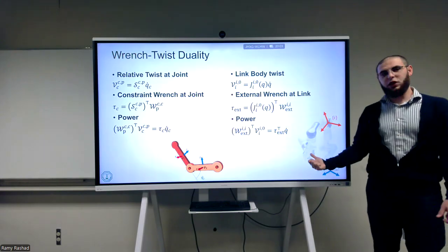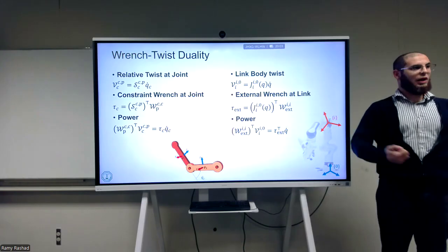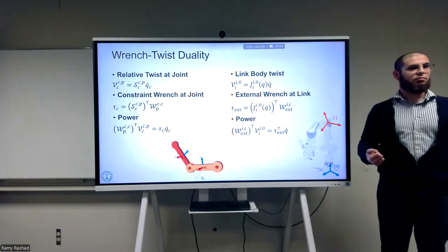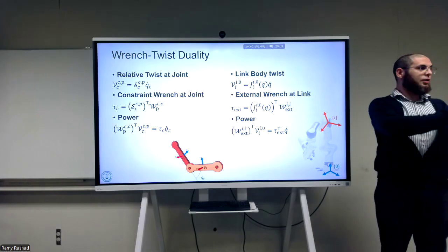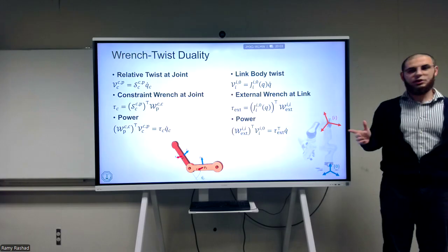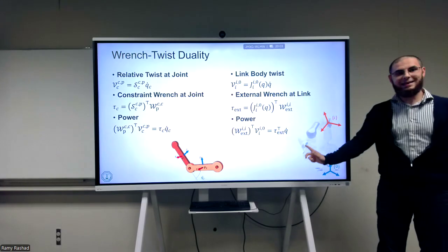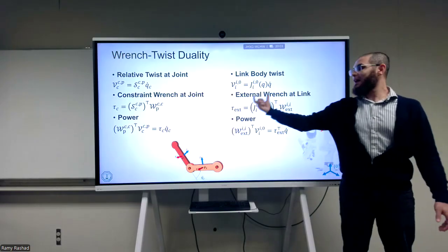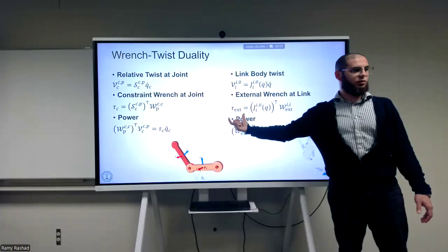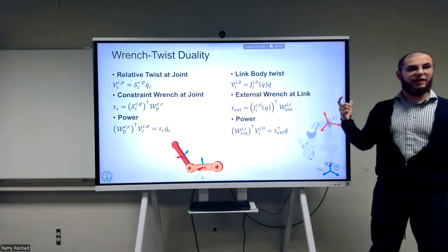So, for example, if you come at the end effector and you start pulling it, what will happen? All of the robot will be affected, exactly. So there will be a torque applied on all of the robot. That's the whole idea, right? So if you apply something at the ith link or at the end effector, you're going to have an equivalent torque corresponding to that. This expression will come later on. You'll see it's very important.